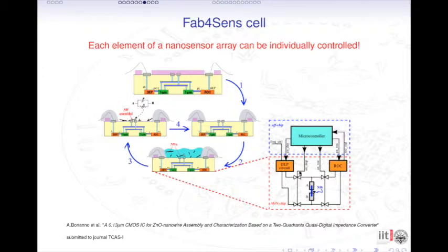You must decouple the electrodes from the DEP circuit during the readout phase, and vice versa. You have to decouple the readout circuit from the DEP circuit during the DEP phase. This is because the DEP circuit works at 3.3 volt and the readout circuit works at 1.2 volt.